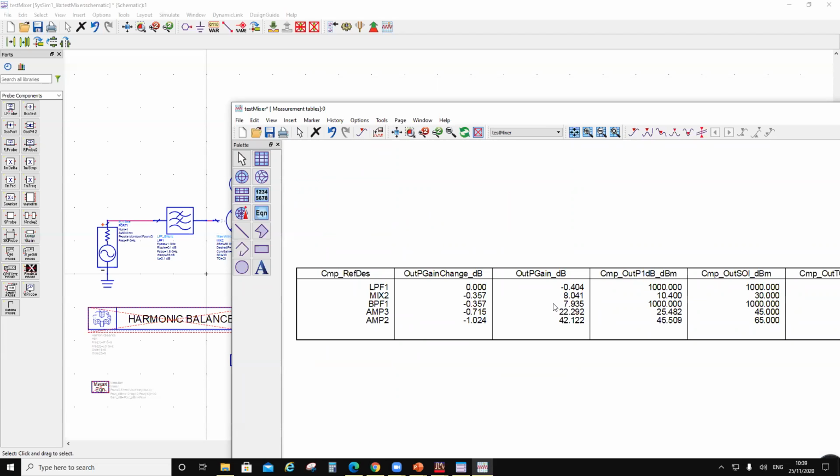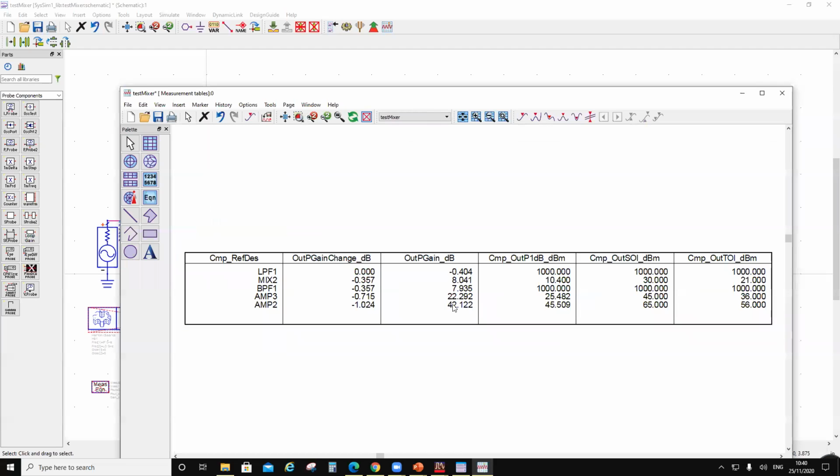And what is the output power, right? Output power is 42.11. So this is a 1 dB compression point actually. So 1 dB compressed gain is around 42.11, right? So the gain contribution from the mixer is 8. Then this is doing nothing. Then the amplifier is doing a 22.5 gain, but it is compressing by 0.35.